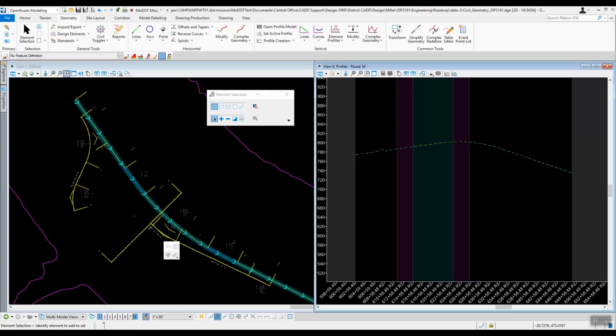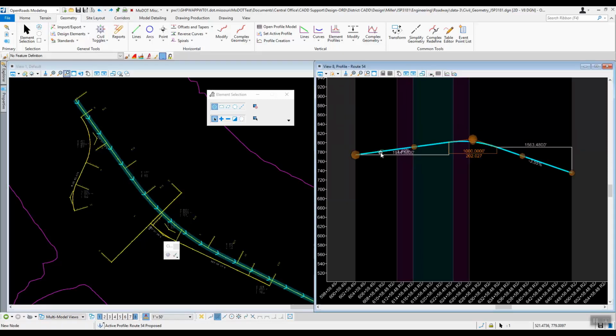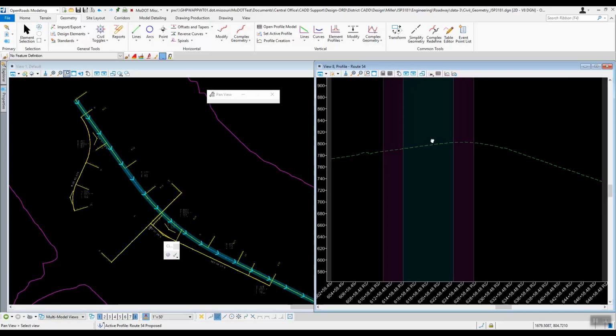Alright, so let's dive into it. Since we've already worked in this one before, the first step in there was to delete this old profile out, so you can select it, get the heads up tool on it, and there's a delete option out towards the end. Okay, that was step 1 in this second portion of this exercise.